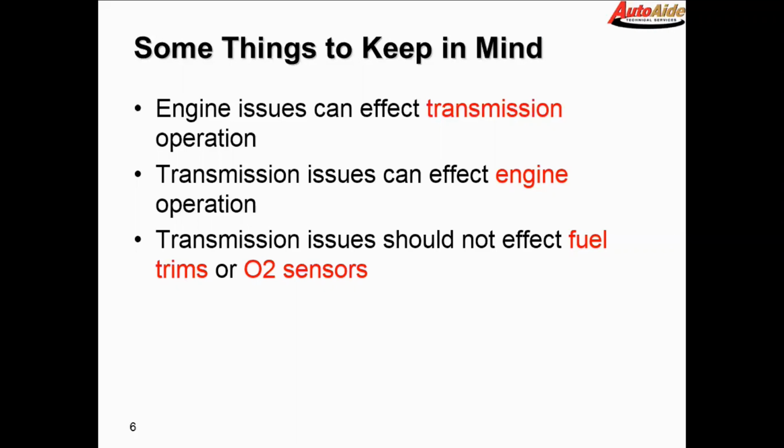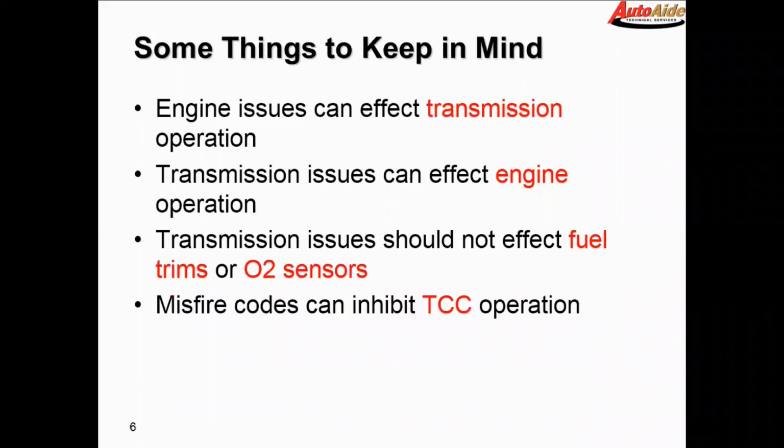But if you get in and your trims are all wonky and it's shifting early or whatever the case may be, then I would go after the fuel trim stuff first, get the engine running right, and then come back and re-examine the transmission after you've got the engine sorted out. Some other things: misfires can inhibit TCC operation.